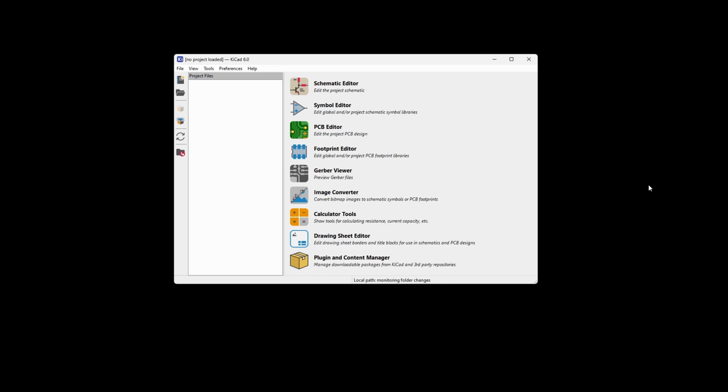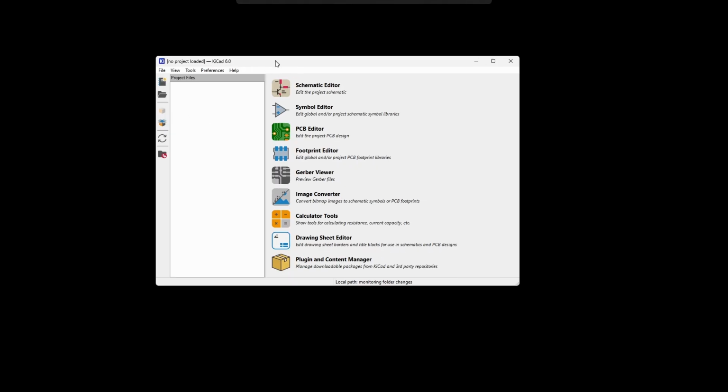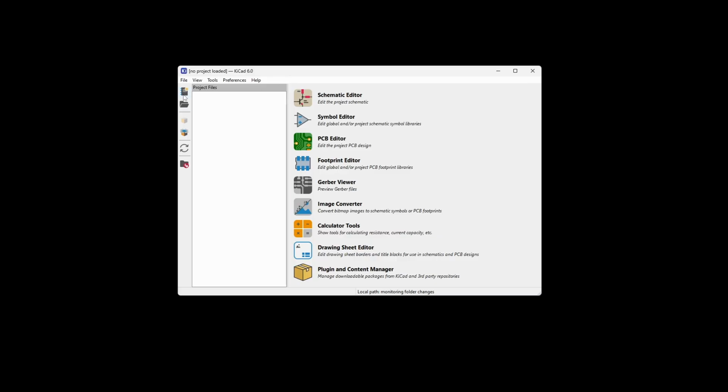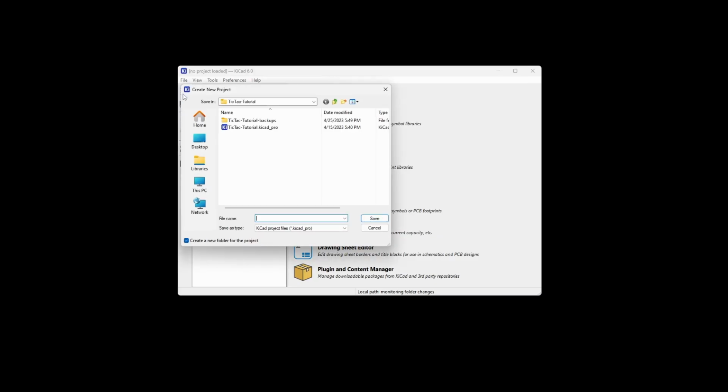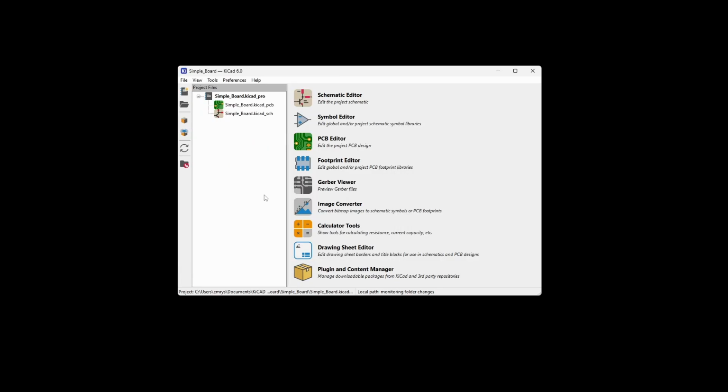In this video, I'm going to be showing how to build a board in KiCad 6. Once you have the KiCad system open, we're going to click on New Project here. And then we're going to go to a folder, which I've already made, called Simple Board, and give it a name. Then we can go into the schematic and start adding components.